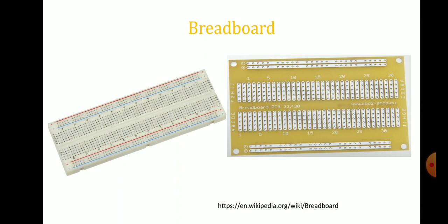Suppose we use a second IC also, once more we need the same power supply. For providing logical inputs, either 0 or 1, we also need the power supply. So commonly we take the power supply at the bottom or top, or if we are using two different power supplies, for example 5 volt at the bottom, and if we are using 12 volt, we can use it at the top. Accordingly the breadboard is designed.